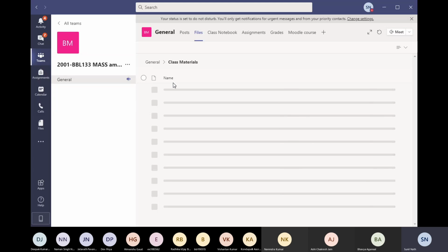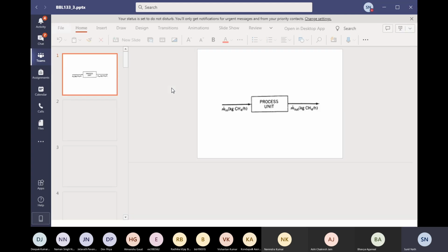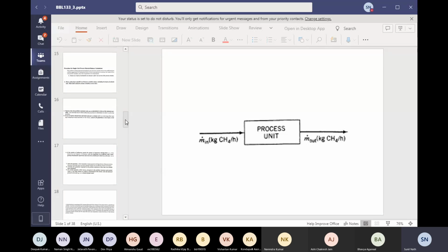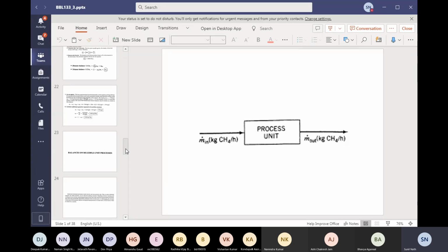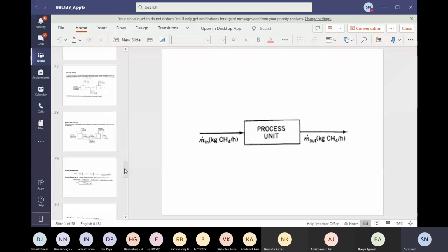Doing it about the evaporator is possible, but then I do not know the combined feed to the evaporator, so that's an additional unknown. While if I do it on the crystallizer, I know that some F is going into the crystallizer, and I know the amount of crystal C that you already found out from the overall balance. You know the amount of mother liquor S, and that plus R has to be equal to what you're feeding into the crystallizer.